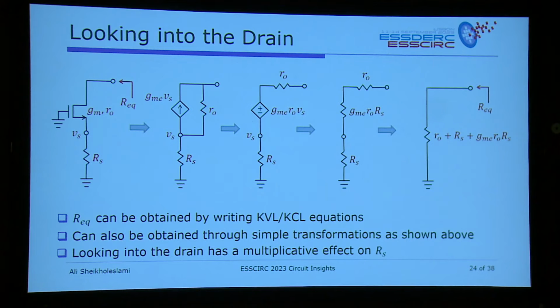And you can do this for every single element that I showed you, and this is what I do in my class and in Circuit Intuitions. You can see it. But the effective thing at the end is that you see, well, this is what's happening. If I have a resistor, and I put it in the source of a transistor, that becomes another resistor, and that resistor is gm ro times Rs plus some other values, but this is probably dominant here. So if gm ro, for example, is 10 or 20, what you're saying is that this circuit is a resistive multiplier. It takes a resistor, multiplies it by a value, which is relatively large, gm ro, and I see it from the drain. So that's the intuition that you get out of it, but you see, first of all, it's a resistor, and then you find the value of it.